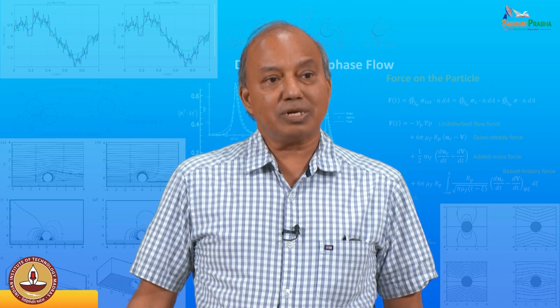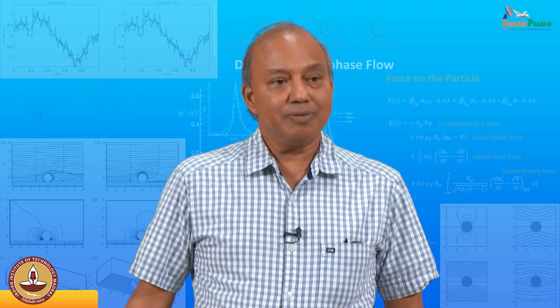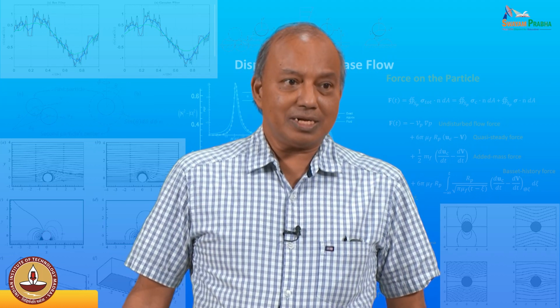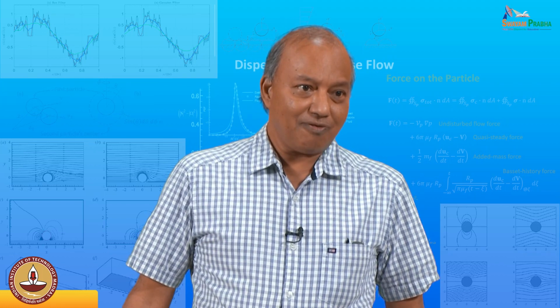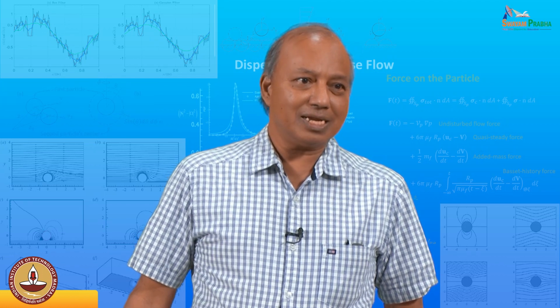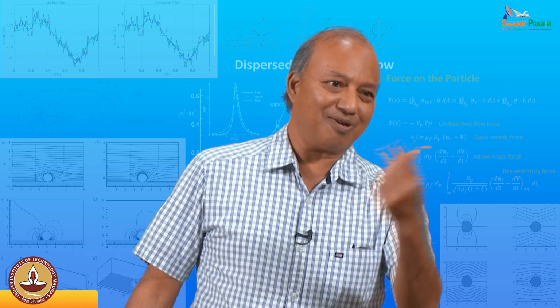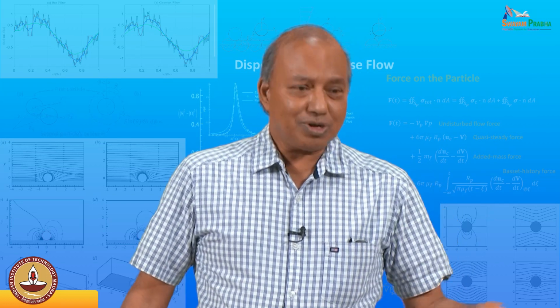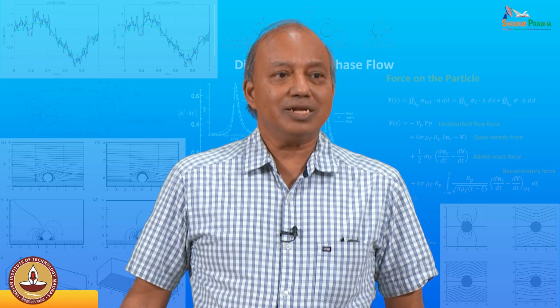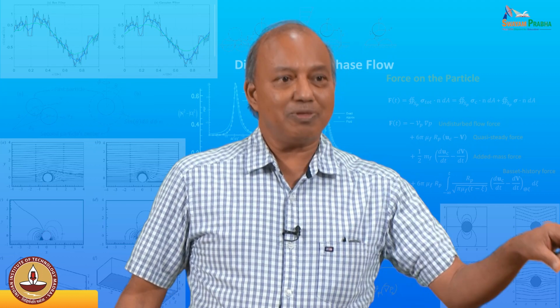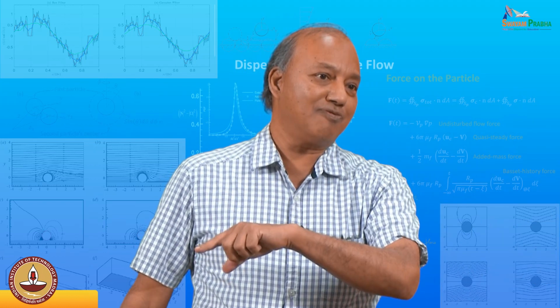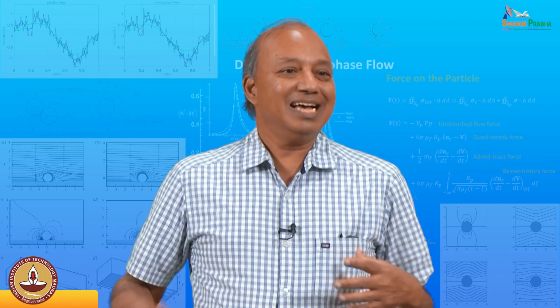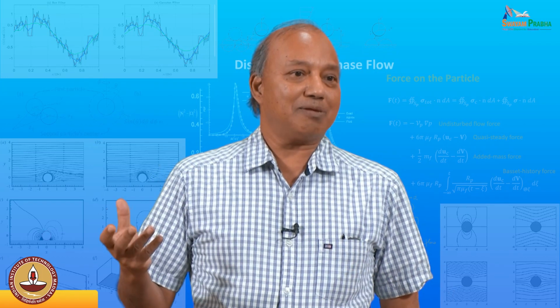Now, if the Stokes number is order 1, then the particle still obeys the fluid, but it's a little adamant. It just keeps going out, or if it's lighter, it will come inward. I will show you later in this lecture that you could calculate from the particle velocity what the fluid velocity should be, because it's still not like a baseball being thrown.